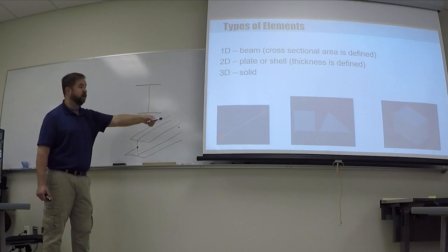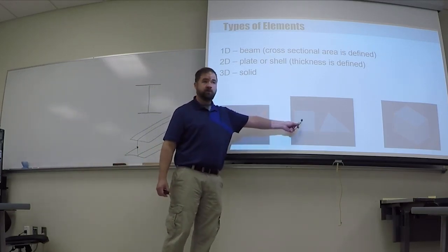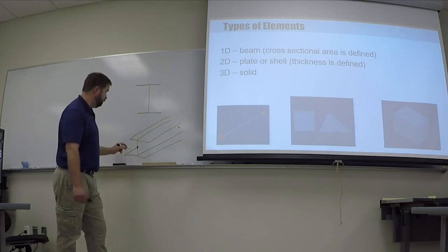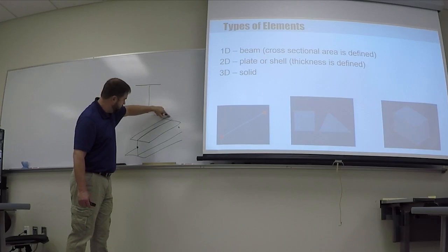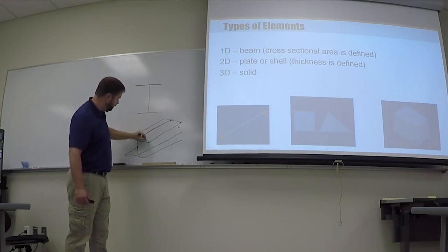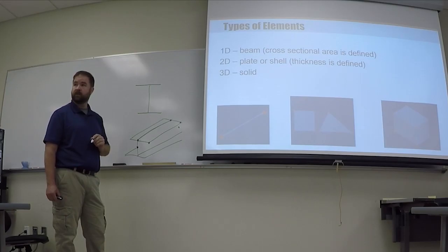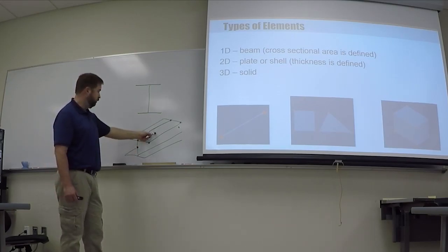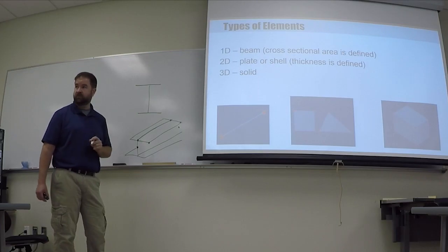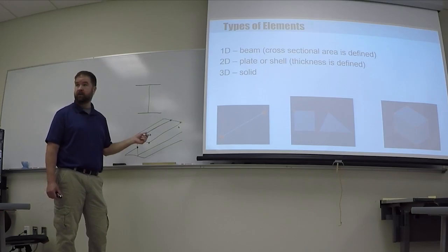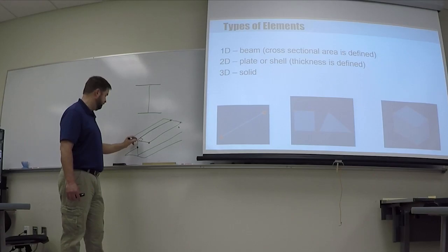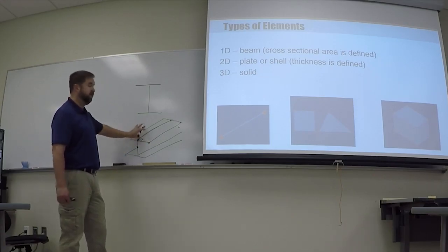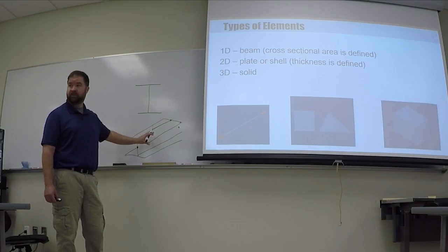Okay? Now, if I want to use 2D shells to do this same thing, I could do a single shell element, where these are the corners like this. Okay? So there's 1, 2, 3, 4, 5 of those. Now the reality is that if I was going to do this, I'd get horrible answers if I did it that way. So I really need to break this shell down into smaller pieces. Well, let's just say I did those 5. It would be a horrible model, but let's say I did those 5.